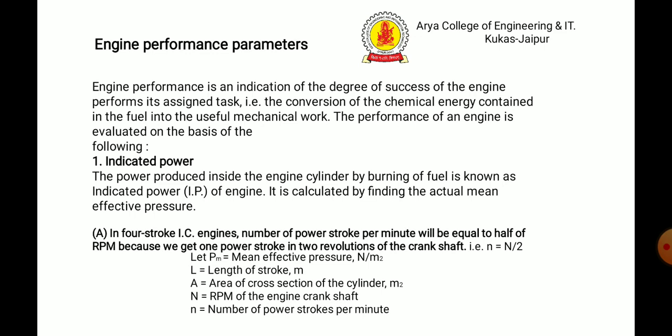Engine performance parameters. The engine performance is an indication of the degree of success with which the engine performs its assigned task, that is, the conversion of chemical energy contained in the fuel into useful mechanical work. The performance of an engine is evaluated on the basis of factors like indicated power, brake power, friction power, mechanical efficiency, thermal efficiency, air fuel ratio, specific consumption of fuel, etc. So the first one is indicated power.